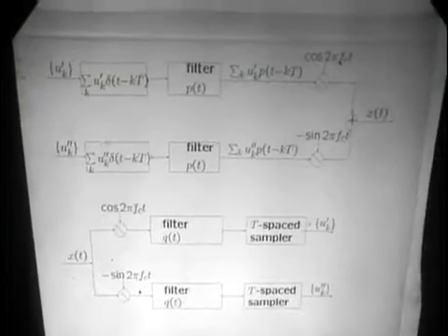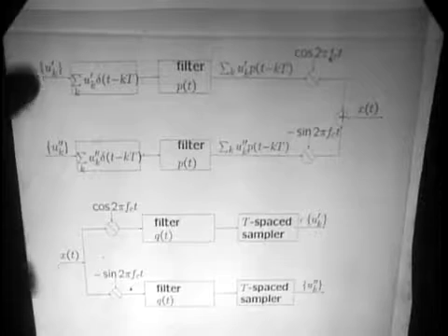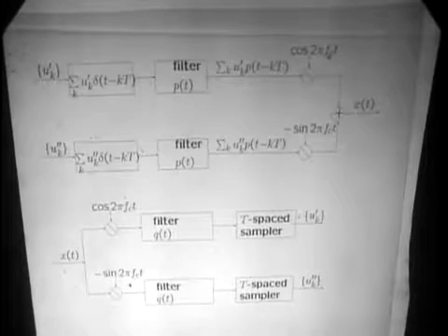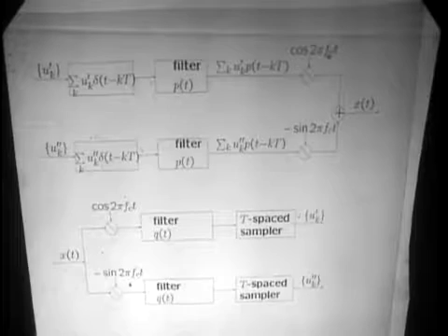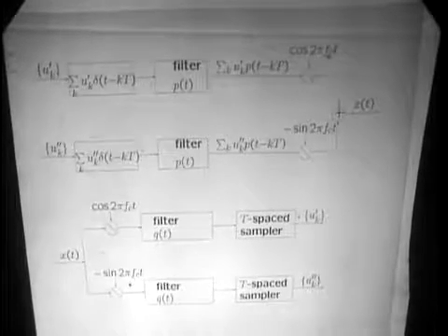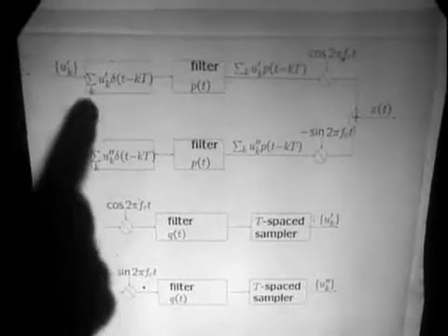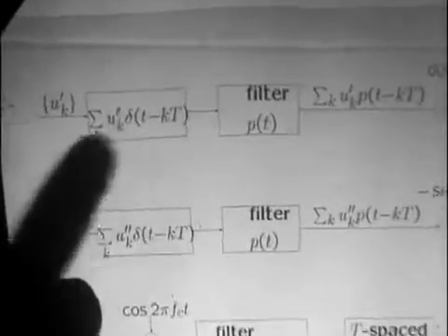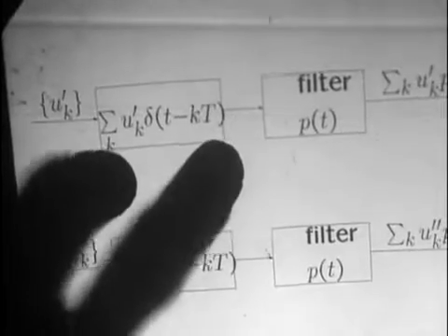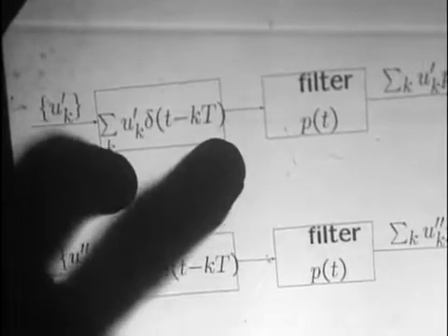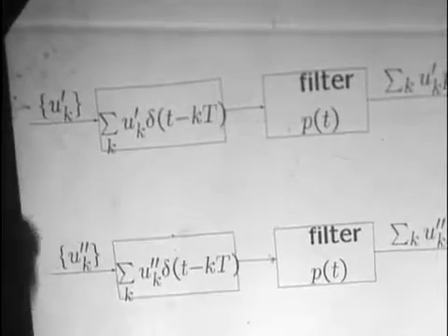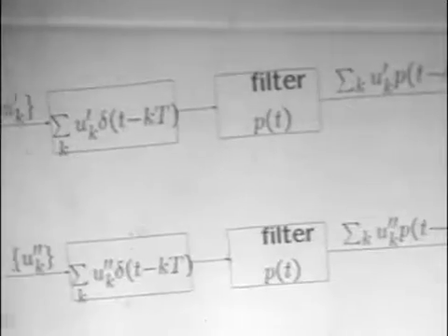We said that what we were doing with QAM is we're trying to essentially build two PAM systems in parallel. So what we do is we have two different data streams coming in. Each one, there's a new signal each T seconds, T being the time separation between times when we transmit something. So the sequence of symbols comes in. What we form is then, well, actually, this isn't a real operation because everybody does this in whatever way suits them. The only thing that's important is getting from here over to there.